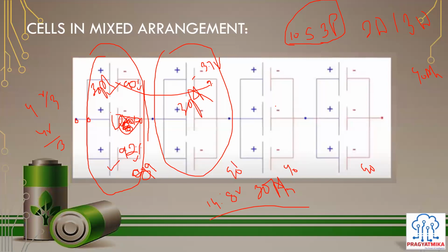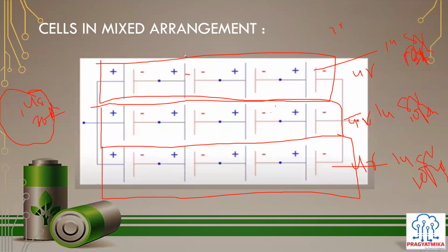But with this master-slave arrangement we were talking about, in that case also the slave is going to monitor the module-level voltage, it might not be at the cell level. No. If we have to do so with multiple slave BMSs, the arrangement is that these slaves are like a pack of, say, 10 cells connected in series. So for each cell, these BMSs can connect, and all these slave BMSs will communicate to a master BMS. Yeah. So we get more sensing points using the master-slave communication. Okay.